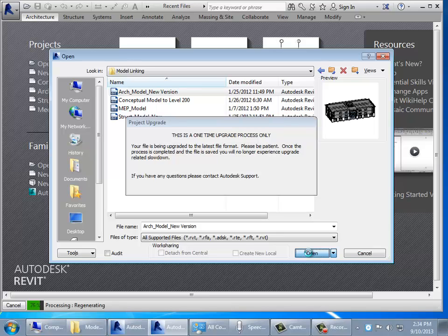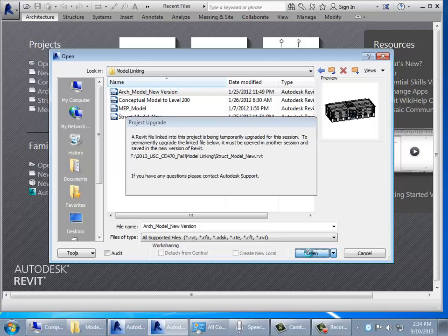Something to watch out for: make sure that as you download it, I think you've all previously downloaded software, probably all are working with 2014, the new version of the software. One thing to watch out for is files aren't backwards compatible. So if you work in 2014 in a file, and you go to a machine that has Revit 2013, it won't open the file. It's always forward, but not backwards.